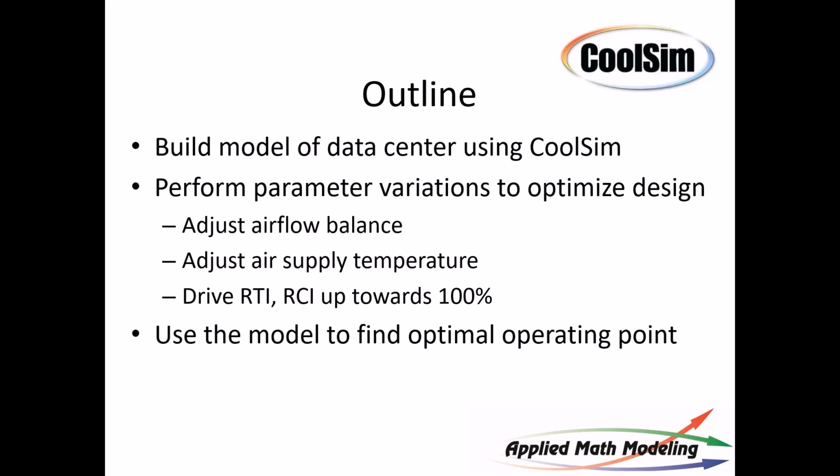One of the most recent ones that I see is a non-raised floor data center using fan walls. It's a popular design. And I'm going to be using sort of an amalgamation of that design that I've seen from other places. And then we're going to take it in its form, which is unoptimized, and we're going to optimize it for airflow, air supply, and then we're going to tune it, essentially, thermally, to try to find its optimal operating point. Interestingly enough, this operating point will be minimal for energy, generally, and also best for thermal efficiency.